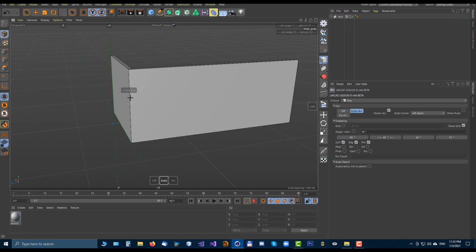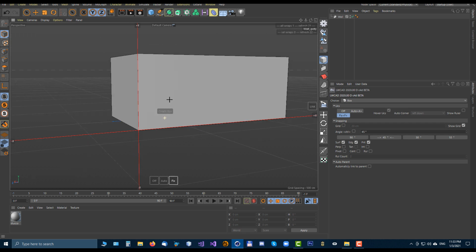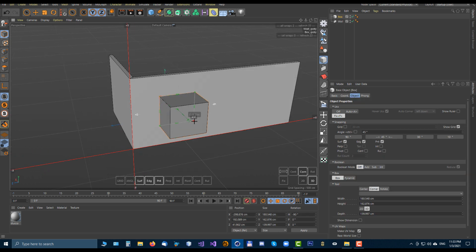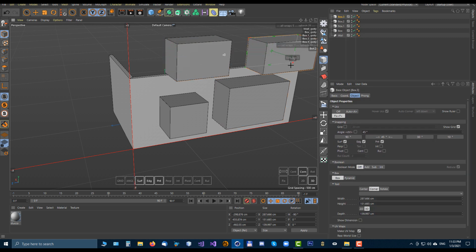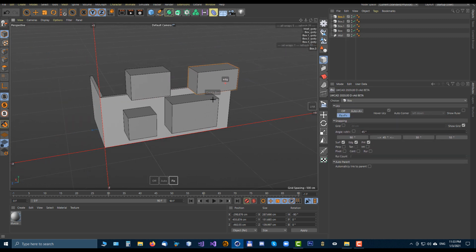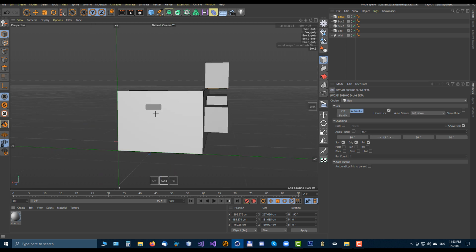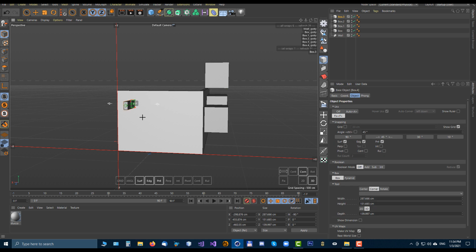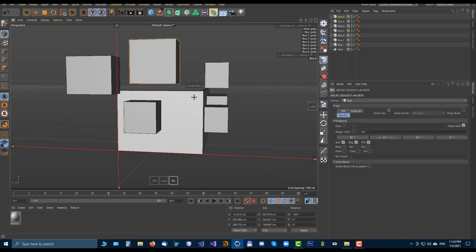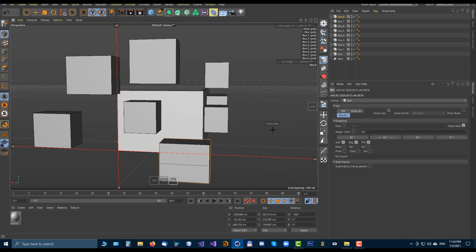So this is a very easy way to set up the UCS quickly before you create an object. Now when I fix the UCS here on this polygon, you can create more objects very easily, and if you need to switch to another, you just hit the A key again, hover with the mouse to another place and hit the F key again, so it is frozen, and again you can create objects on this UCS plane.